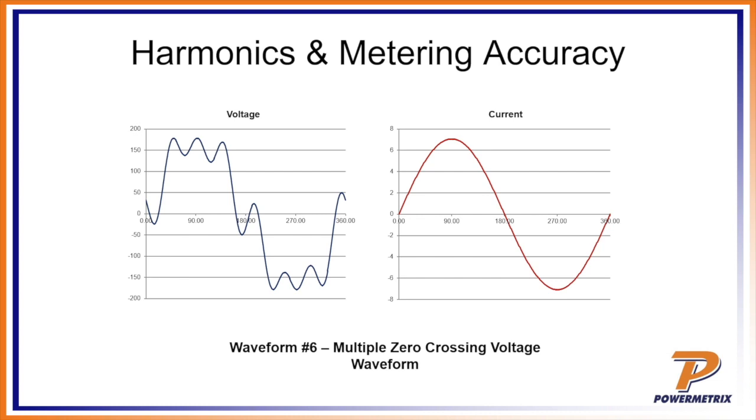I will say personally, I've gone through about maybe 2 or 3 different computer laptop power supplies trying to use those cheap inverters. If you want to invest, get yourself a pure sine wave inverter, basically meaning that it filters out all the harmonics for you. If you care about your equipment, because once again, that square wave is not going to do your equipment any favors.